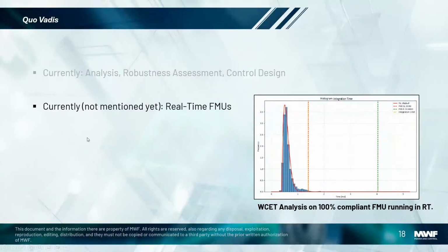Currently, what was not mentioned is that we take these very same models which were used to design and verify the controllers. We generate real-time FMUs with them, with the exact very same models, and export these FMUs to be used in our real-time hardware in the loop platform.